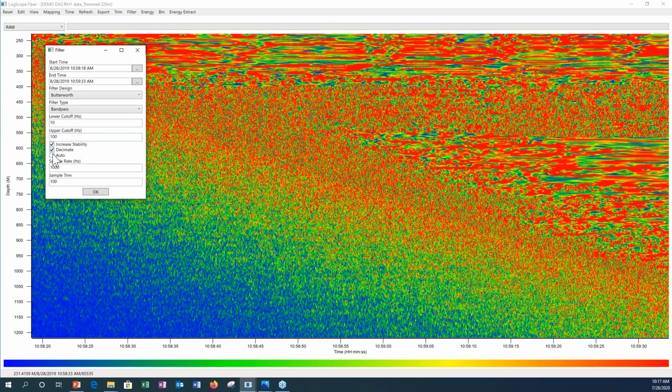We've got a couple of different options on the filtering here; some of this is part of our development process, and we'll probably get that to a single option. But we can decimate the data, which is key because at 5 kilohertz we still have a fairly large data size. So we may want to reduce the sample rate because we're only cutting off at 100 hertz. There's an auto feature, which is very nice, which takes the guessing out of it and selects a nice sample rate to handle the frequency band. So we can output that.